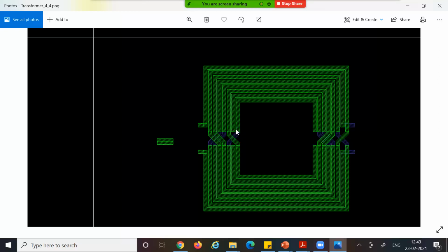But in the previous case, you connected the endpoints, right? Actually, you'll have to zoom in and see in the actual layout. This is a snapshot of the layout. It may be that they have connected it in metal 6, because you can see there is one square here, like there is one sort of a cut. So it's possible that it is going in the bottom metal layer to just short these two. I don't know if it's the secondary side or something.